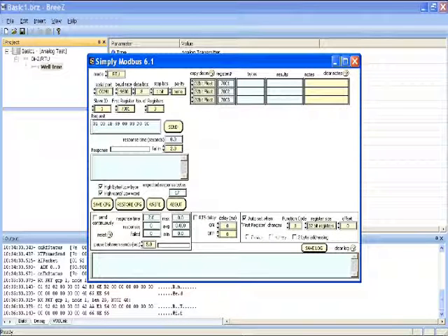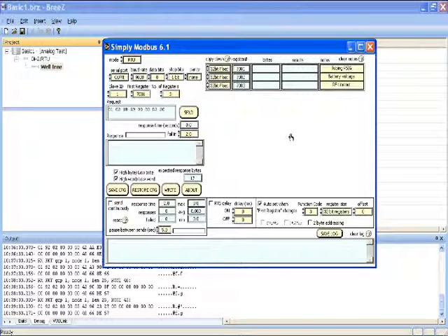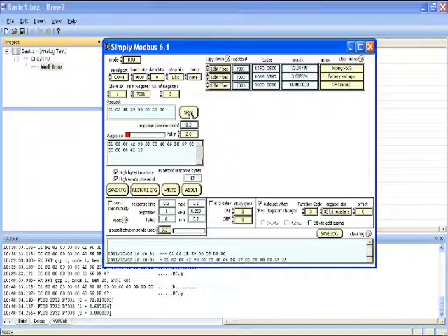Today I will be using a software called Simply Modbus to emulate our request block. We are going to be asking for the first register of 7001. The number of registers is 3. Once you have your request block ready to send and you have completed your wiring between the DH2 and your RTU or Modbus master, today I am doing 232 and have wired to my Phoenix connector from my COM1 of my PC. So now I will send the request block.